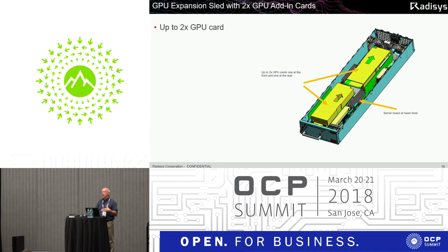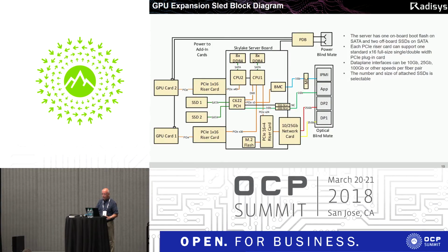The sleds are designed to go up to 1 kilowatt per sled power consumption. And the rack is designed to support a full rack of 1 kilowatt. That would be 32 sleds, up to 64 servers in a rack. So the difference with this configuration is that on the left, we changed the 4 DSPs to 2 GPU cards, but everything else is the same.